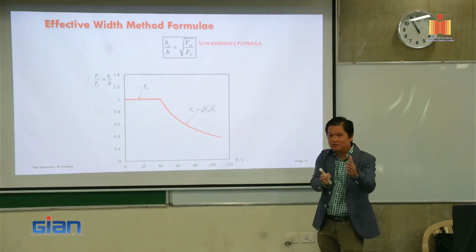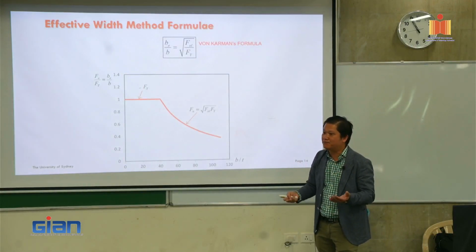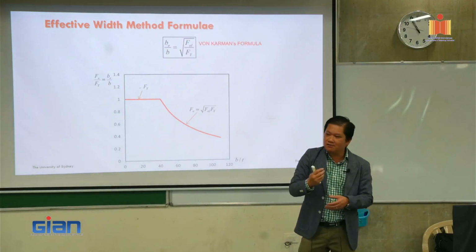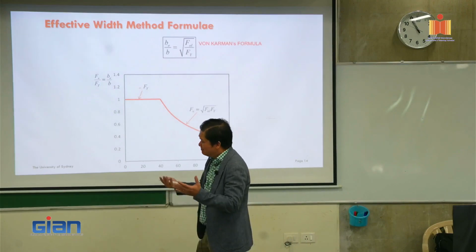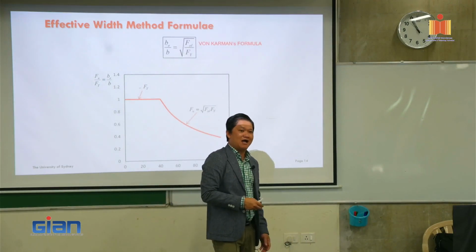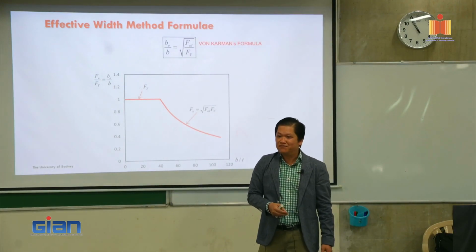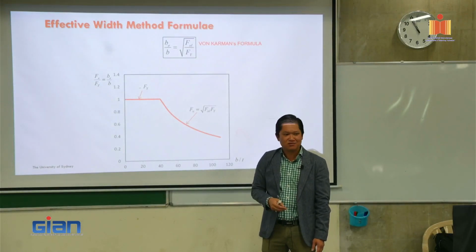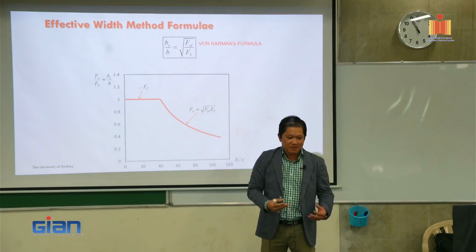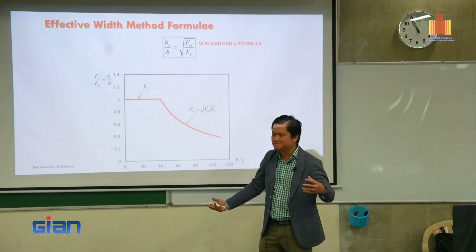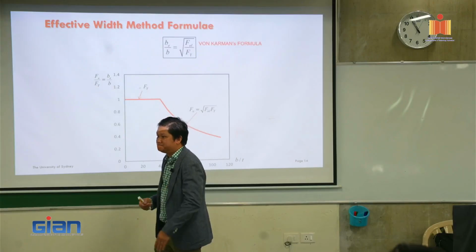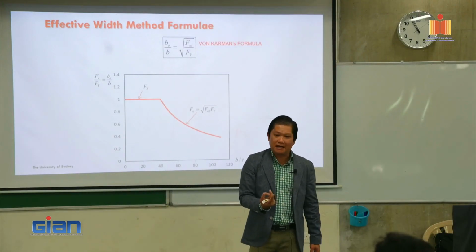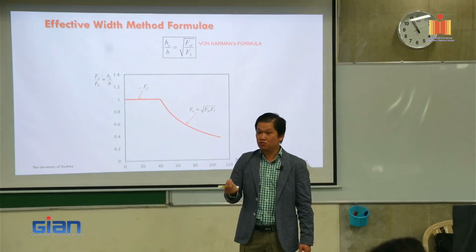So he takes post-buckling and everything into account, but in practice, they scratch their heads and say, oh no, in practice our member is not 100% straight. There's a bit of imperfection there, so it might affect the strength. So we need to think about that, especially with the slender ones. Then you have a bit of a problem. The factor you need to consider is the residual stress.